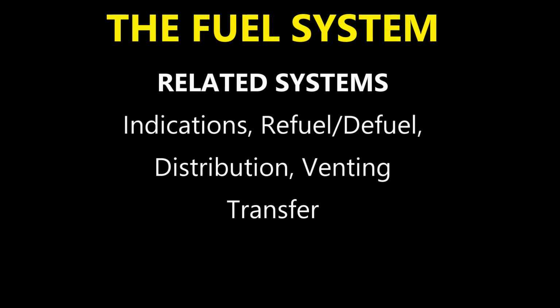Basically, it's deciding or monitoring and making sure that you have center tank fuel to be used first. So if you have the center tank that's empty, fuel then is going to be used from the inner cells. I kind of went over a lot of the distribution of the fuel, whether coming from the center tank or from the wing tank, because the wing tanks have suction valves. So that's going to happen in the event that the pumps are failing.